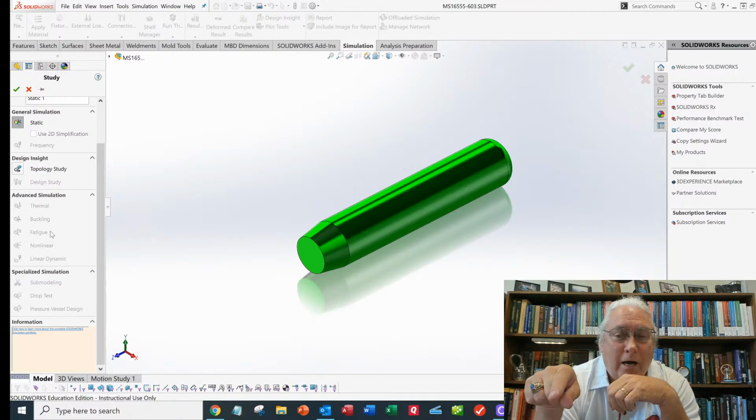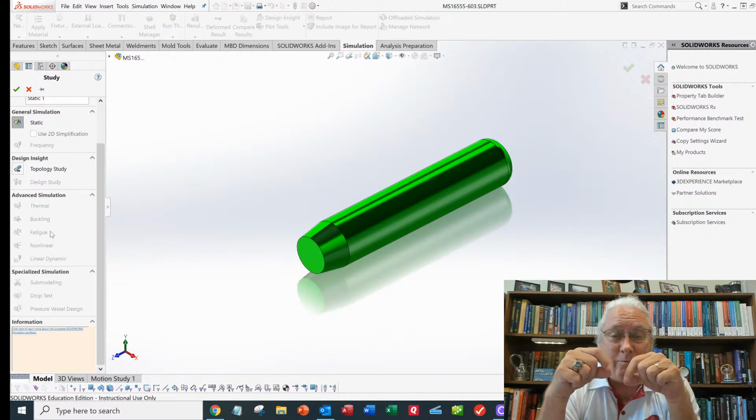And then you build a model, you run the model, and if those don't match, then you've got a problem with your model. You want to make sure the model matches the hand calculations, and then, ideally, you take your test specimen of whatever the sample product is, take it downstairs to Dr. Tate's lab, put it on the MTS machine and pull it until it breaks, and come up with a real answer.